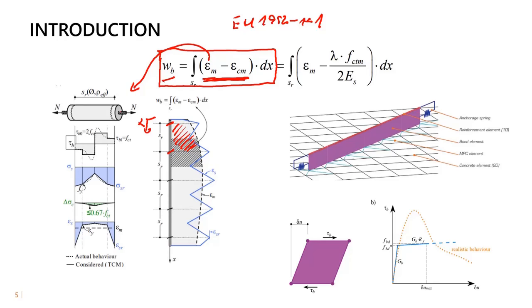If you imagine that you have just a bar that is submitted to a tensile load, and the bar is encapsulated inside a cylinder. In there, some cracks will happen after exceeding the tensile strength in the concrete. But at first there is some crack spacing. This is S subscript R, which is dependent on the diameter and the effective reinforcement ratio inside the structure.